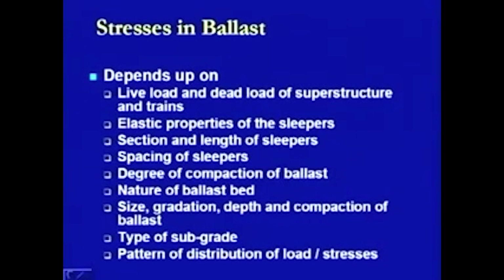The next thing is the elastic properties of the sleepers. If the sleepers are elastic in nature, they will rebound back to their original condition, and therefore the stresses will get dissipated by themselves. The section and length of the sleeper matter: if they are wide area sleepers, they are going to distribute the stresses to a much wider area, but if they are narrow width sleepers, then obviously there will be more concentration of the stresses, and we are not interested in the concentration of stresses.